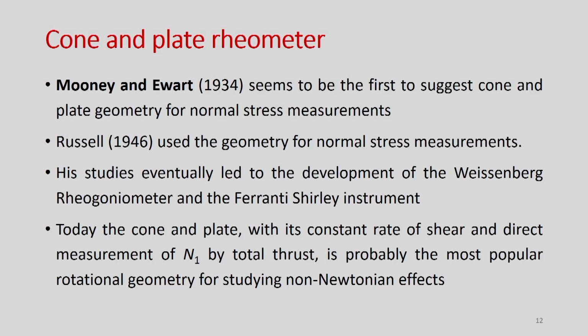So, the shear stress expression is the same for all the cases, but shear rate expressions are different depending on the gap between the two concentric cylinders. One has to be careful in using these equations. Now, we will go to the other type of rheometer, that is the cone and plate rheometer.